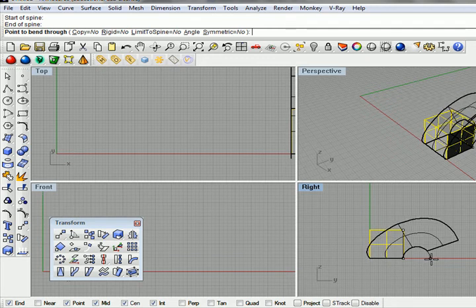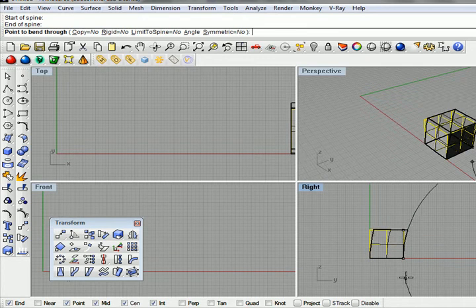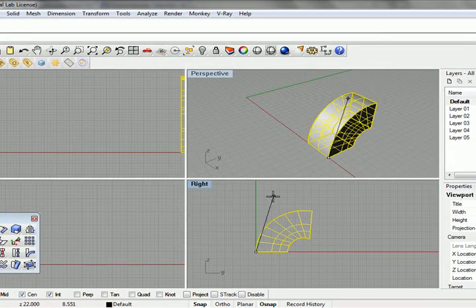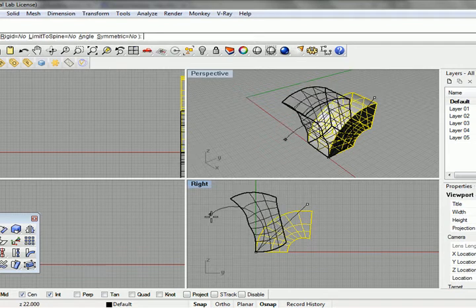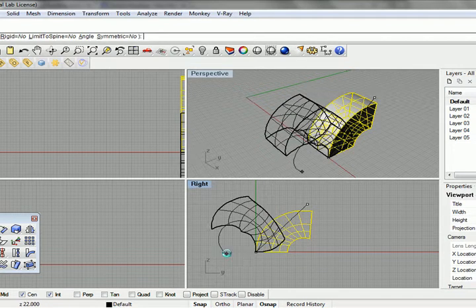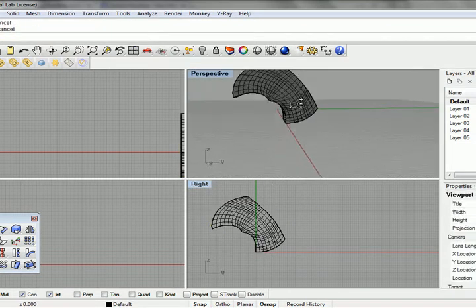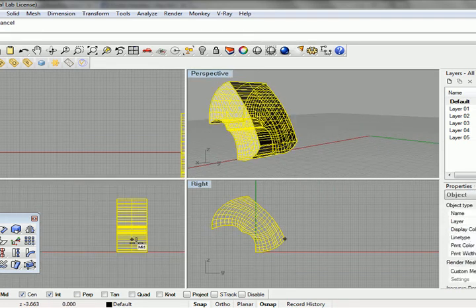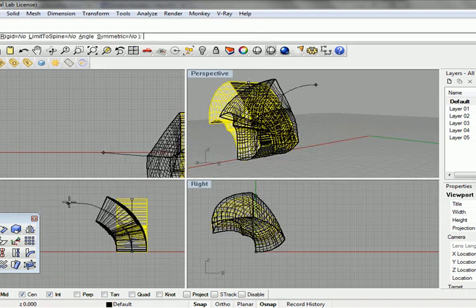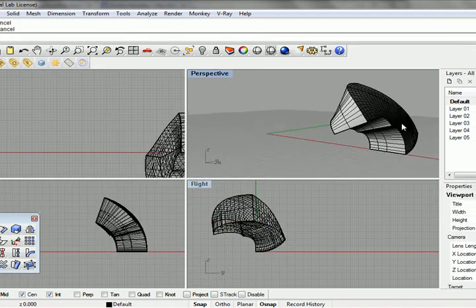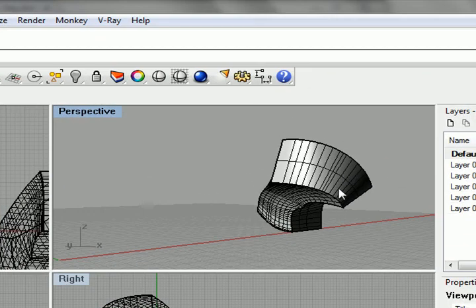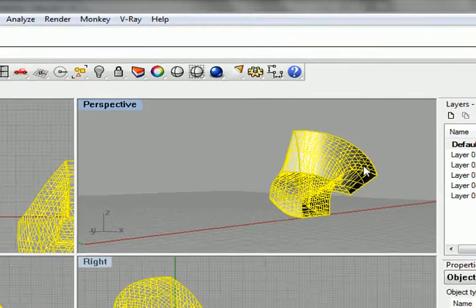You can see how it's distorting some of the other geometries, but you can start to create and bend and reshape some of these guys. You start to play around with this as a geometry set. You can create some really complex forms by massaging this into place this way. And so that's effectively how those four commands work. Split, trim, which are essentially very similar, bend, twist. And then the last guy is going to be fold.